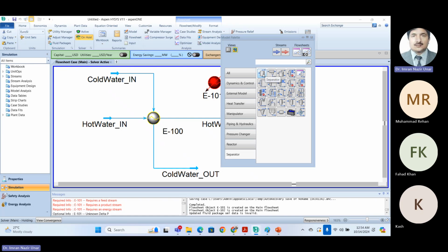They separate things on the basis of vapor phase fractions and density. The flash separator separates streams on the basis of their vapor phase fractions. If any stream is not 100% 0 or 100% 1, but has in-between values of 0 and 1, then you can use this.